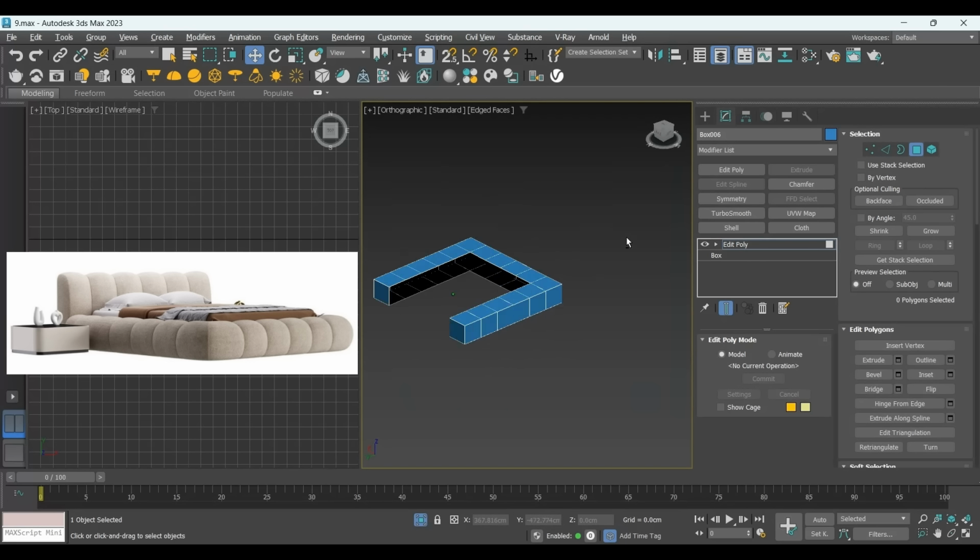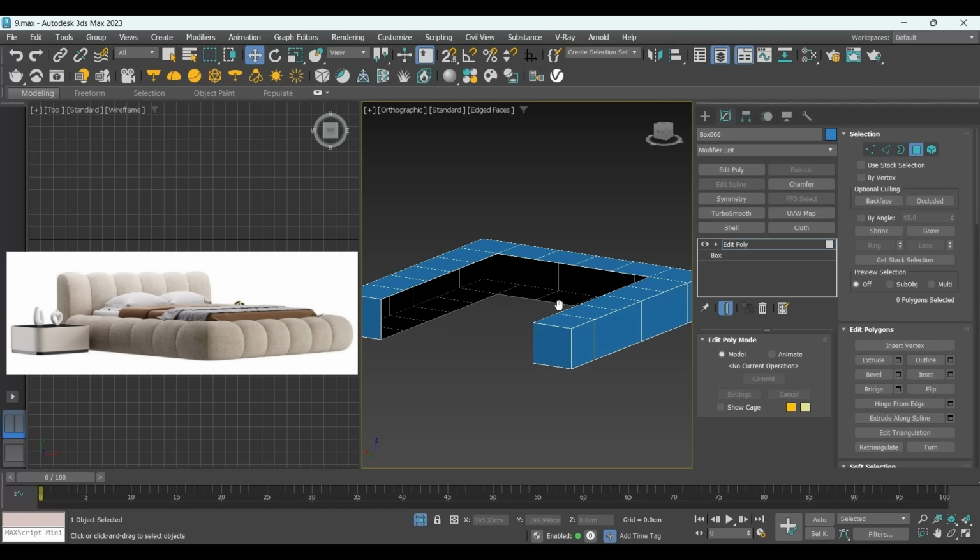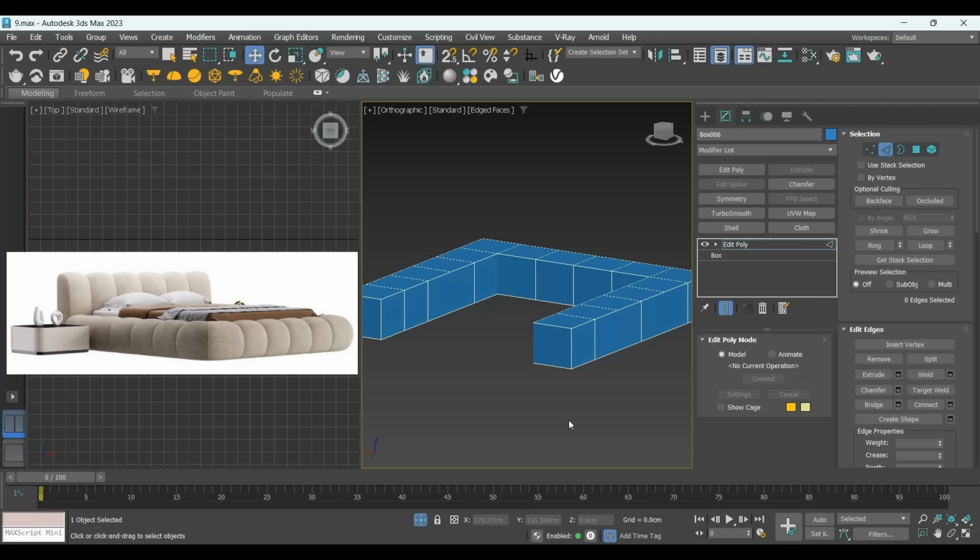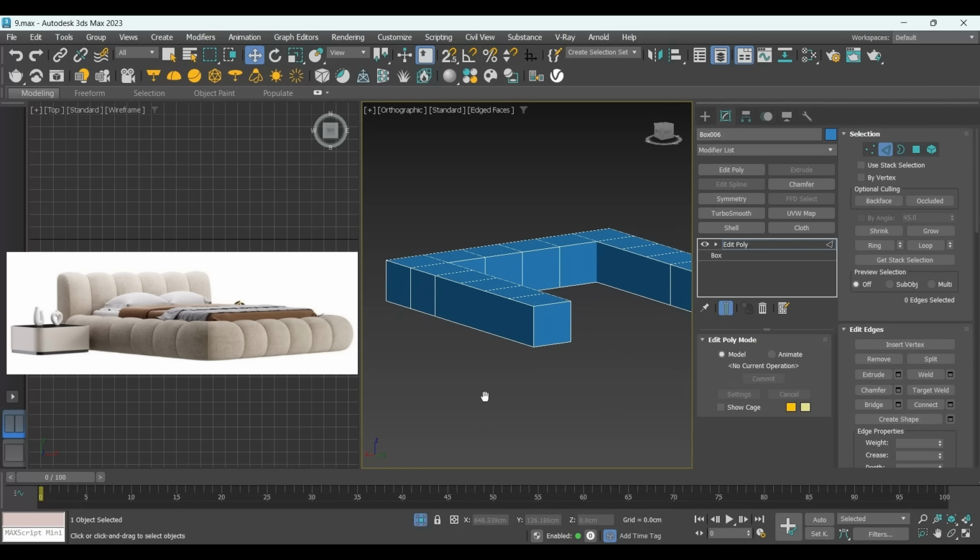But we have an open box from the back side. I need first to select this border and close it. Now I will use Control and click on Edge. So now I am in Edge mode selection with Control. You go from one selection to another using Control. Now I will use Alt, deselect this edge and deselect this edge to use Bridge. Bridge will close this gap from top to bottom, like this. Now the shape is closed from all directions.